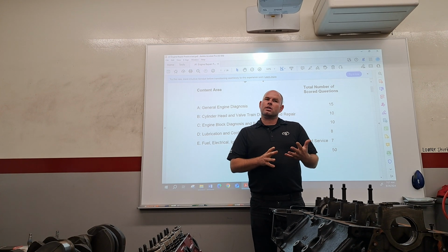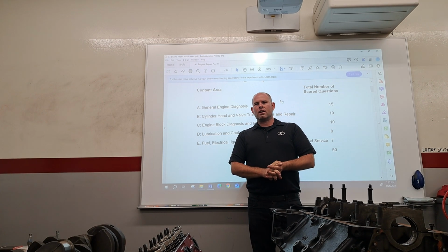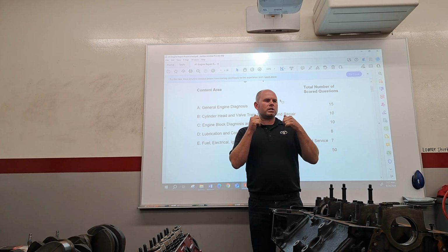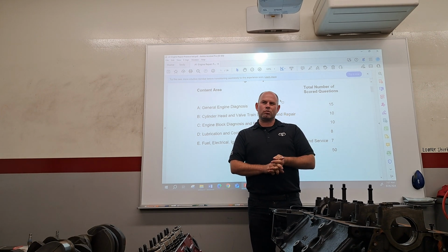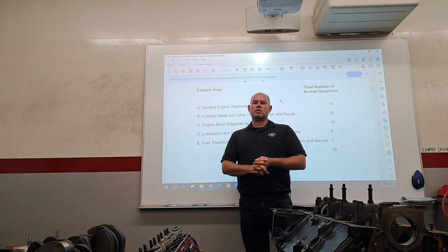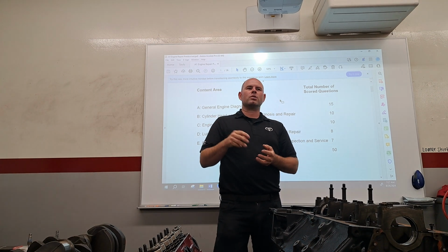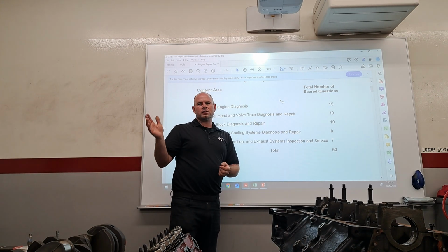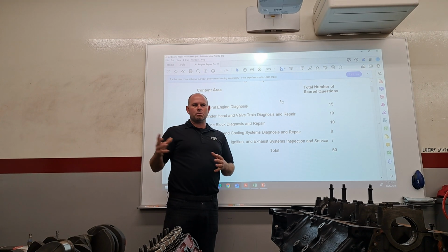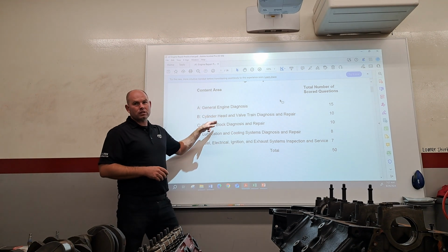Like with the rotor, we've all done that. You cut enough material off the rotor to fix the defect. Well, that's not really true for engine stuff. With engine stuff, you actually have to take a specific amount off to get ready for the next size, or for the size bearing, or for the size piston. So there's quite a bit of machining discussion right there.